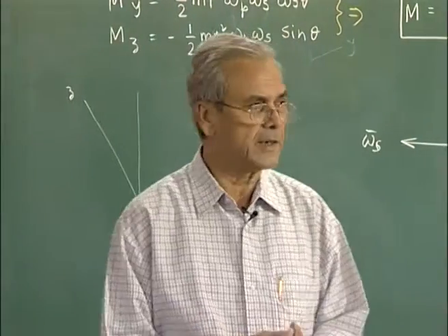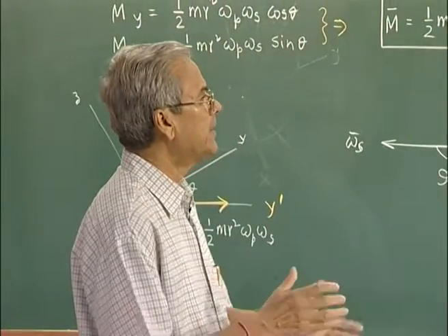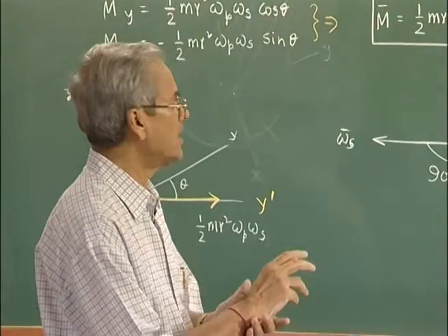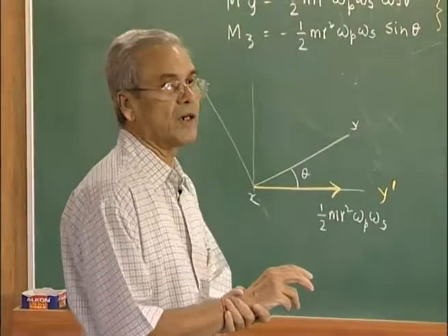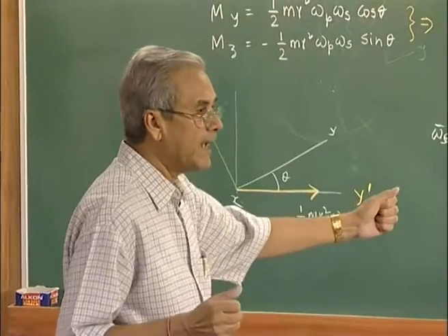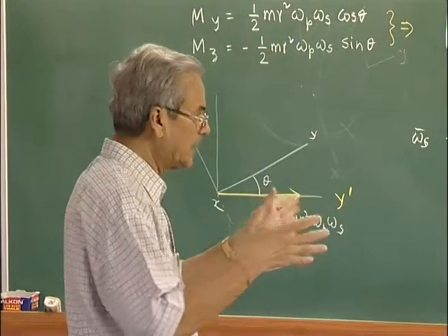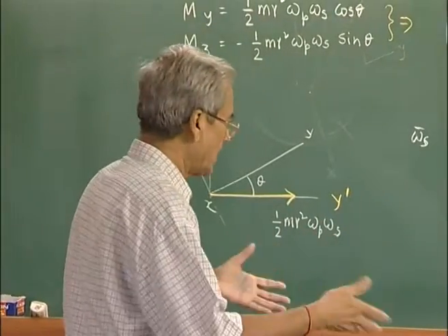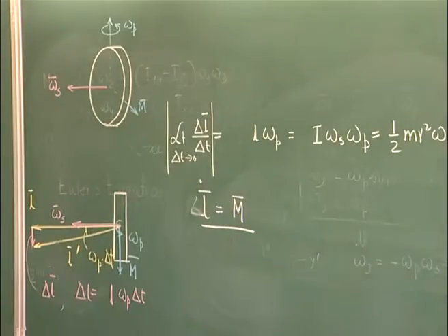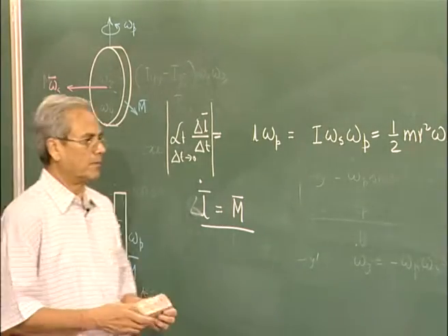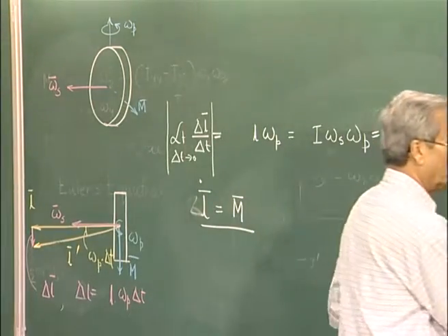So, this has an important consequence for engineering systems, because we have many cases where we have a spinning or high speed rotating disk or rotor or a body, which again is forced to turn its axis or its orientation because of the motion. So, for example, the turbine in say a jet engine.